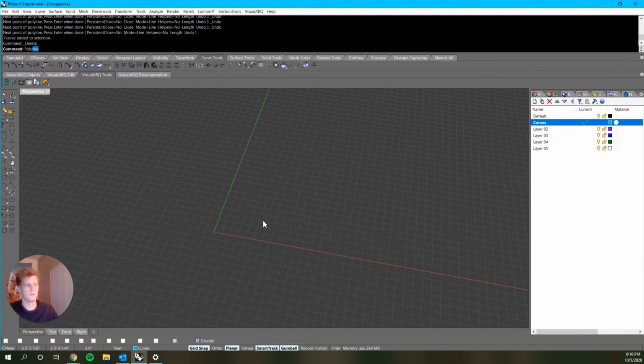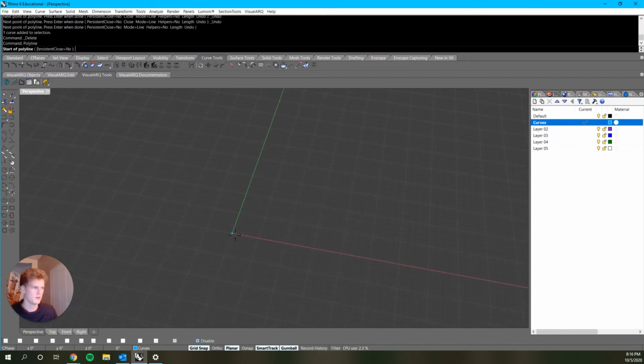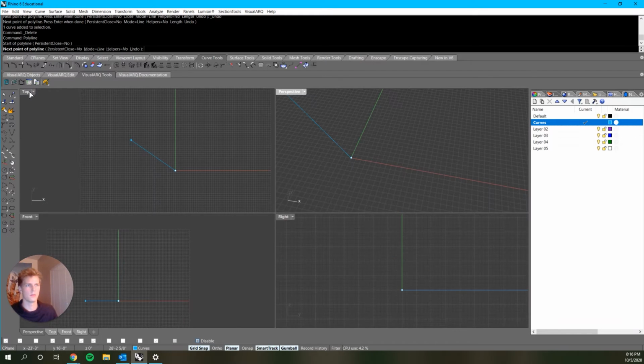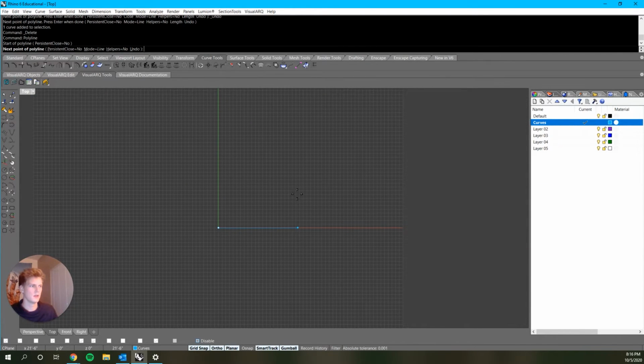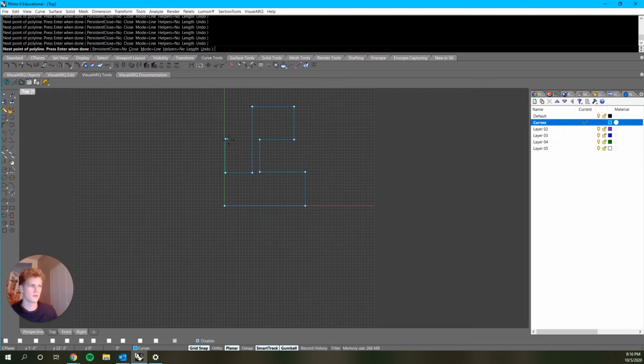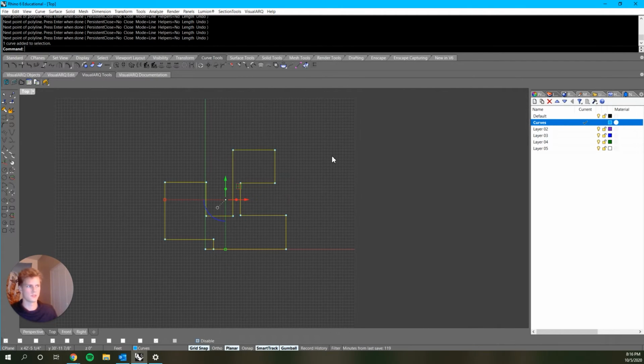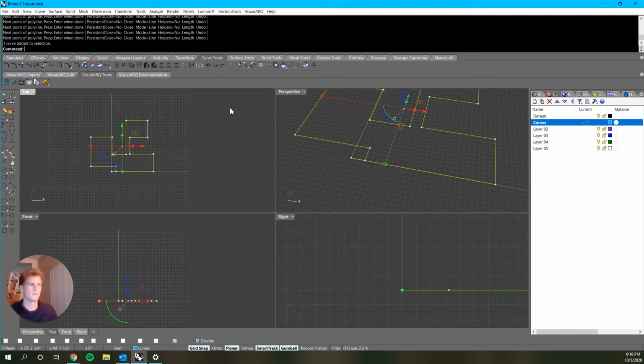So if we make a polyline, we also have the option to hold Shift, and if you'll see at the bottom of your center screen there, it turns on ortho. And that will allow you to draw at sharp 90-degree angles. So in our top-down view, you'll see it here. Every line that you make, if you're holding Shift, will be completely 90 degrees. And that works really well for making something like a building plan, or just sort of snapping in between flat orthogonal geometry.